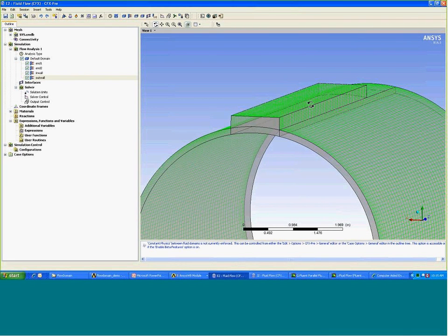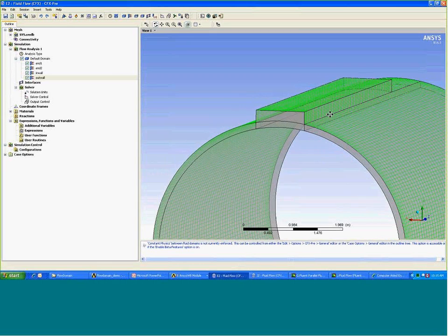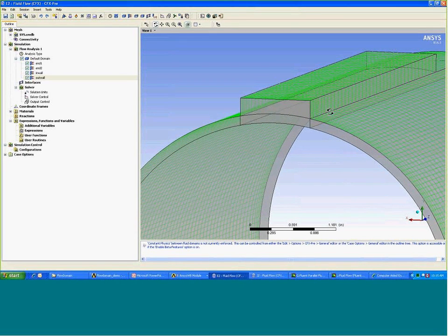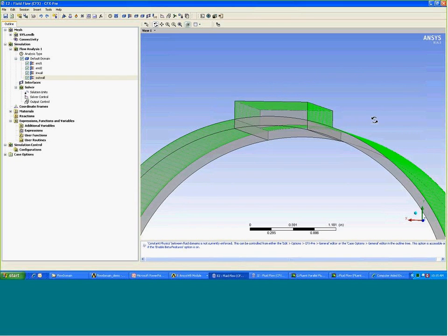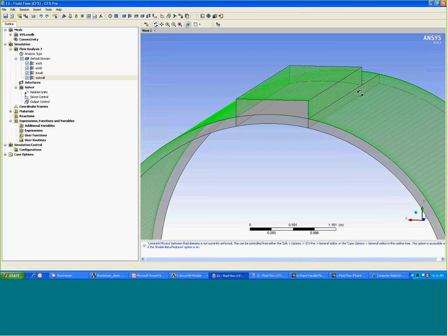Did you notice one thing? In CFX, if I don't assign an external surface, it would be designated as a default boundary, which means it will be treated as a wall. In this case, because of the flow-through mesh, CFX-Pre can identify the contact region.